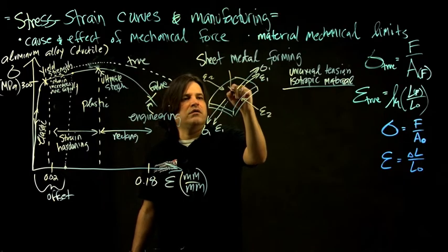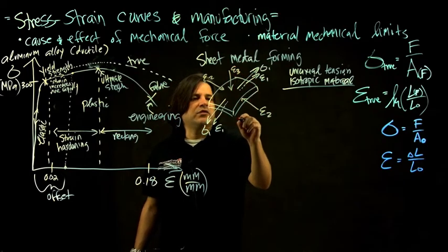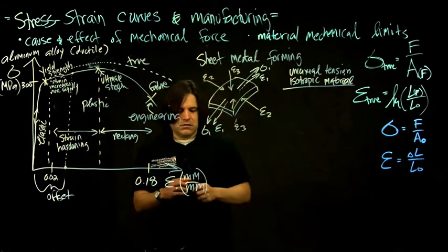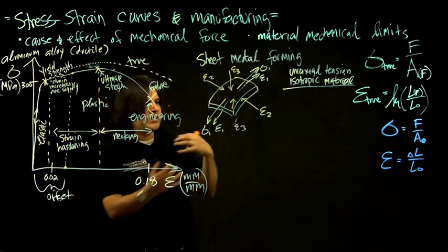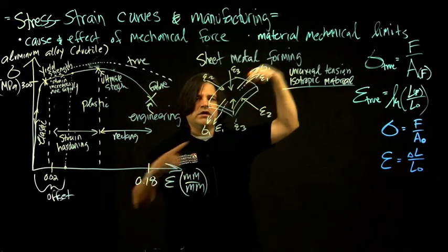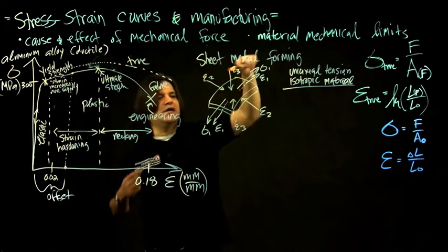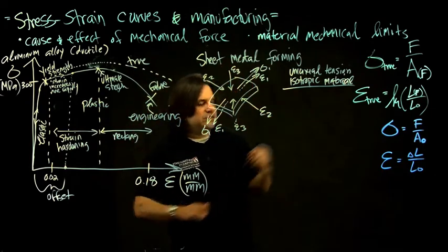In the other three, if we're talking about three dimensions, these other dimensions, this is dimension 3. So even though this is an isotropic material, it doesn't favor one direction, and we're only applying the tension in one axis, this is going to be the response. It's going to feel strains in either direction.